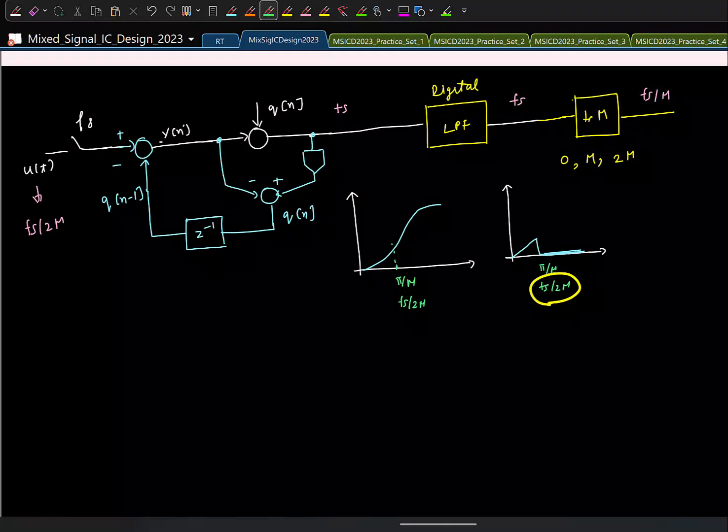So now at least qualitatively we can see that after doing this, the quantization noise present is very small. So I can go and choose a large value for this oversampling ratio, which means the quantization noise present at the output will be even smaller. Basically, if I keep increasing m, now I am here; if I increase m, I will be here somewhere. So the quantization noise will be even smaller. I can keep increasing m and reduce the effect of quantization noise. If the quantization noise power reduces, what can you say about signal to quantization noise ratio? It increases. Effective number of bits increases, right?